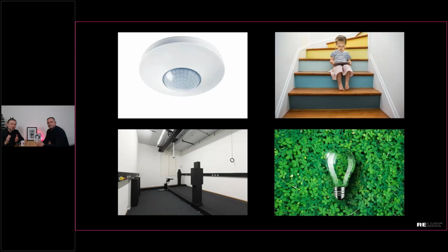It's possible to measure different angles of the sensor positioning, and you can get a digital form of the detection area. This can be measured in laboratories like at METAS, and this data just goes into this tool. So it's just working with measured data. A specialty of the tool is that you can calculate the energy saving by using a sensor in general. That is important, so that you know what you can save with a sensor.